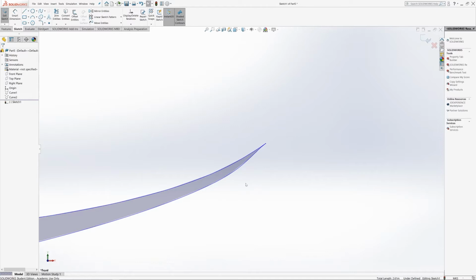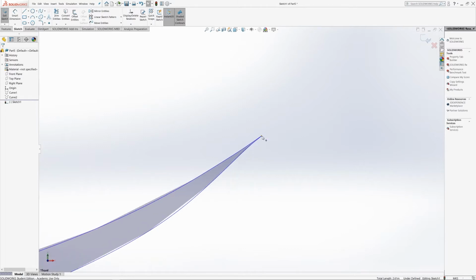Now before I do anything with the trailing edge, I need to get rid of this finite point, because when we come to mesh later on, this point, the sharp edge, will create massive headaches for us in terms of getting a non-skewed mesh. If I try to have an inflation layer around this point, it's going to be highly skewed. There's going to be lots of numerical errors. The solution may not even converge, so it's just bad practice.